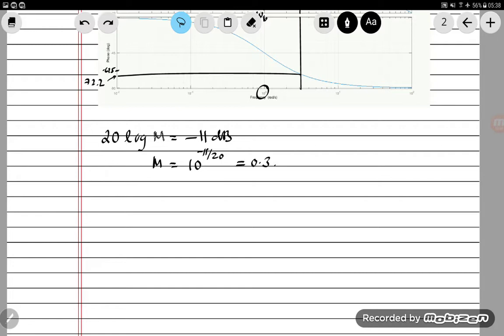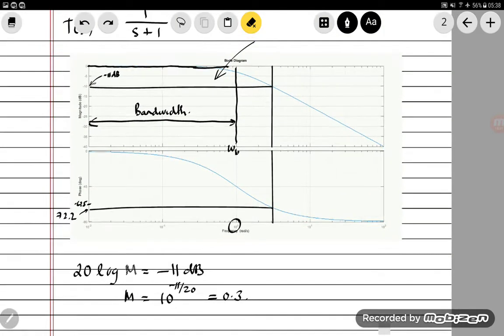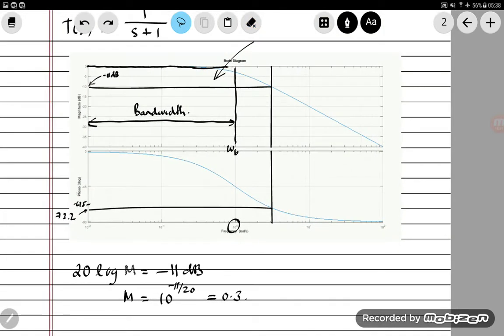Of course we know that the Bode plot consists of two plots, the magnitude and phase plot, and for the magnitude plot, the scale is a decibel scale. So that means it's 20 log of the magnitude of your frequency response transfer function. And this is the angle.